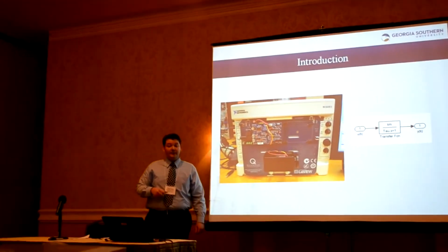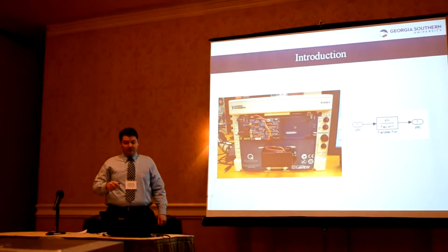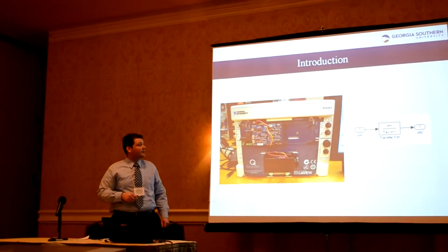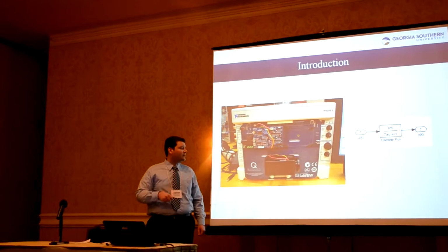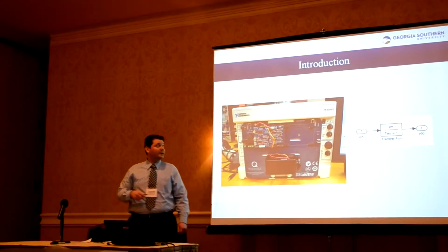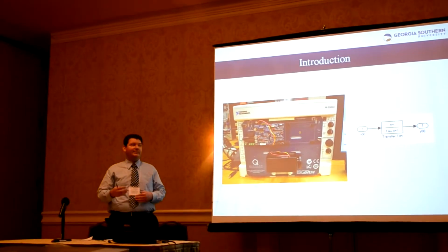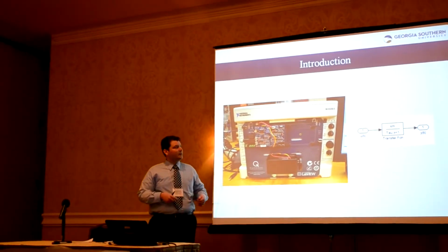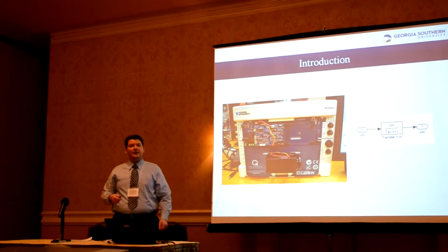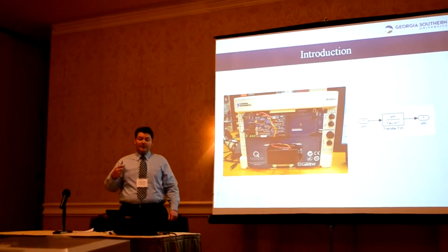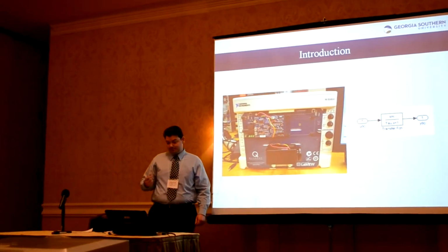Okay, so first, the plant we chose to investigate the system identification technique was the Quanser QNet DC motor control board fitted to a National Instruments ELVIS 2 board for interfacing with LabVIEW. And on the right, you can see a block diagram of the scheme we used to first gather system response data.